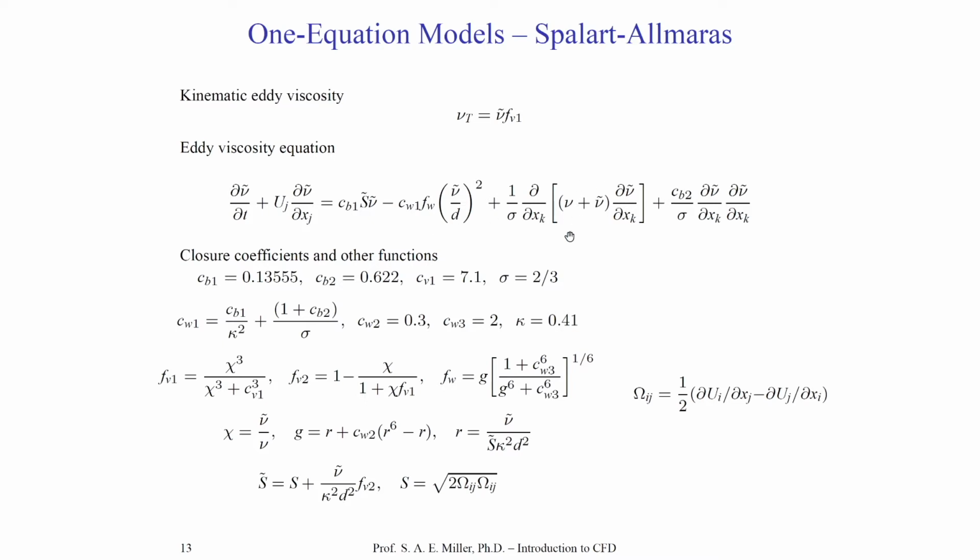You can see that they use some of the similar approximations for particular terms, just like the models that followed Prandtl. This term here should look very, very familiar to you now, because of course it was developed in this very class. The other terms, of course, are connected to closure coefficients, which are all listed down on the bottom of this page. Take a few minutes to study this particular model to fully understand it. Now you'll see they have a kinematic eddy viscosity. This is a core idea in the model. And of course, this represents an algebraic equation, which is being solved during the solver process.